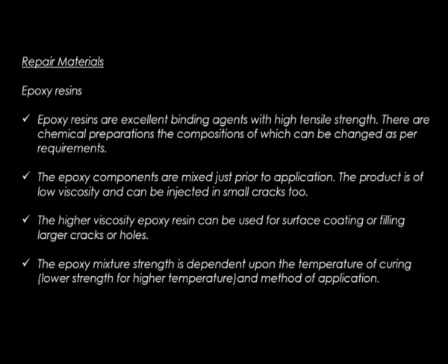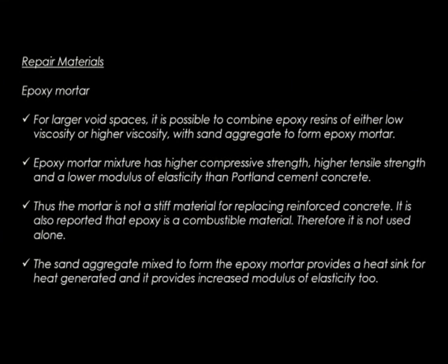Epoxy resin strength depends on the temperature of curing and the method of application that we follow. There are multiple methods of application of epoxy resin. When epoxy resins can't be used for larger void spaces, we mix the epoxy resin with low viscosity or high viscosity sand aggregate, and that mixture is called epoxy mortar.